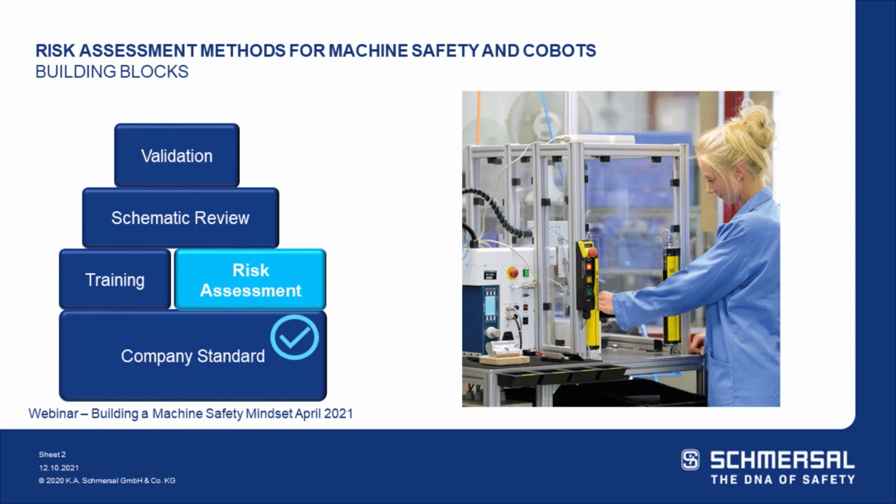So I started my investigation, and when I asked to have the machine cycle, I noticed that when I broke the light curtains, the machine completed its cycle and then stopped. So the engineer who designed the safety circuit portion did well. But if a risk assessment was done, I feel more questions would have been asked and the machine behaviors analyzed to provide a solution to prevent the press from completing its cycle after the beams were broken. A risk assessment could have prevented the amputation on a machine that gave the operator a false feeling of safety because light curtains were installed.